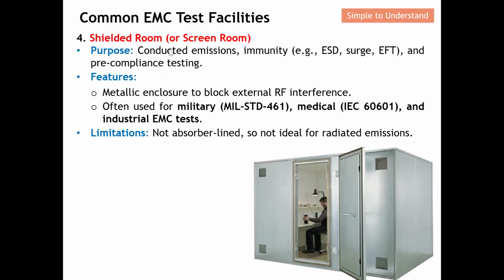So all this conducted emission, conducted immunity, even ESD, surge, EFT, can mainly be performed in a shield room. The key feature is you just have a simple metallic enclosure, in fact, to block external RF interference. So whatever signal is outside will not be able to come inside the chamber. This is often used for military MIL-STD-461, medical IEC 60601, and also industrial EMC testing.